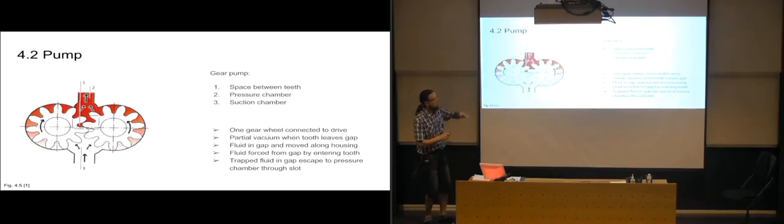So on the back side here, there is actually more room, so that the back side of the teeth here are not touching the casing at all. So they actually have some room for the fluid to escape on the back side of this tooth, so it can just go behind it and up instead. Then you won't get the pressure problem in there.